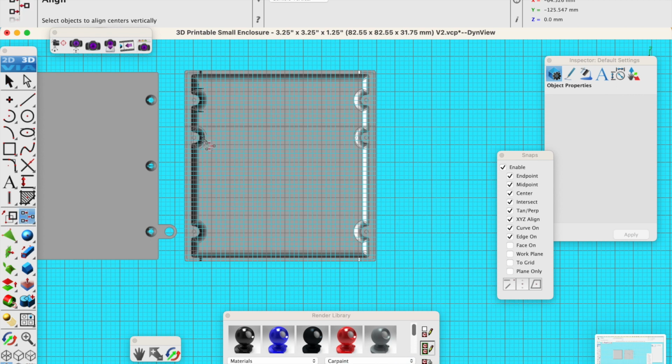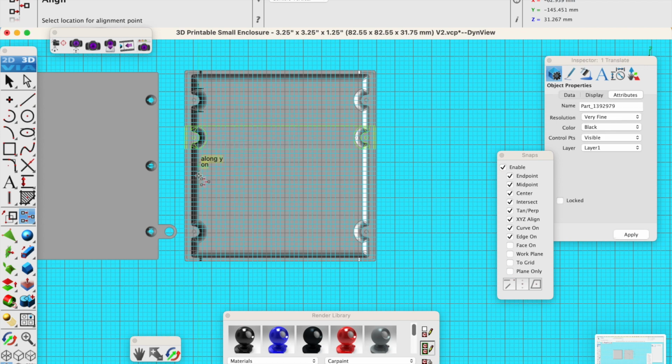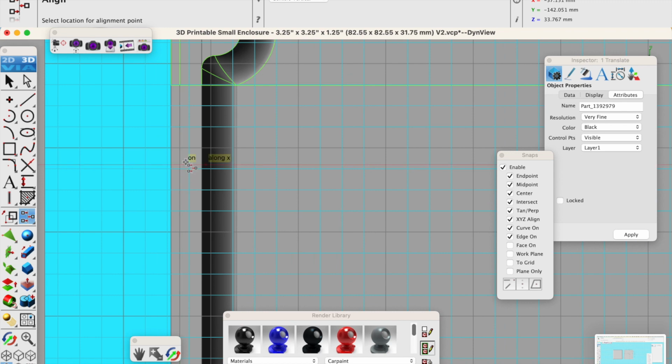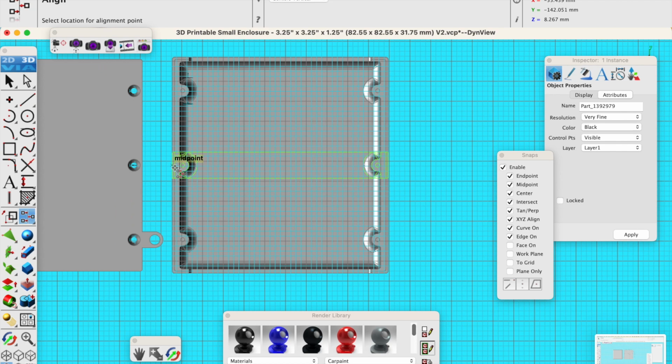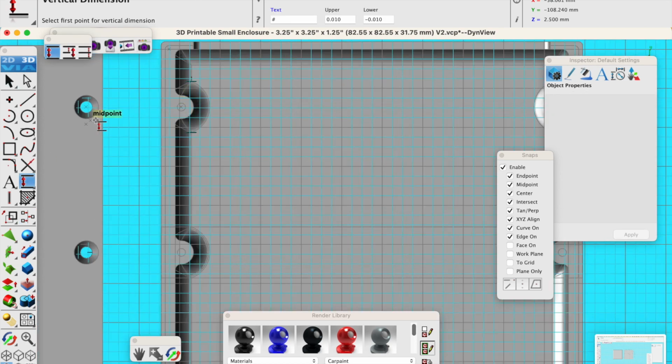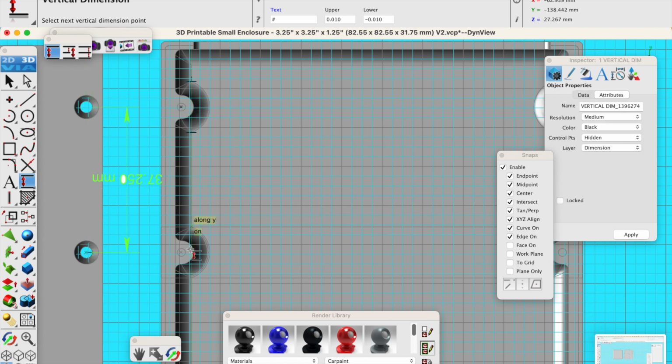We're going to do an align. Choose that piece. And we will align the point. Right, before we join, this time we'll do our measurements again. Should be the same as this, which is 37.250 center.